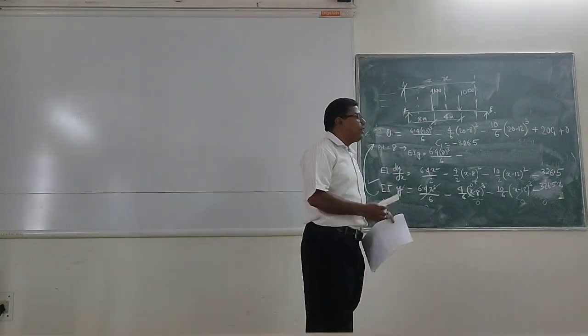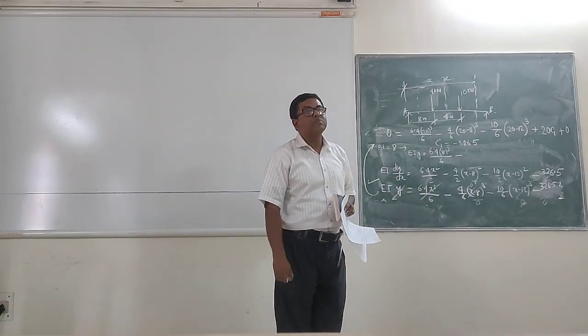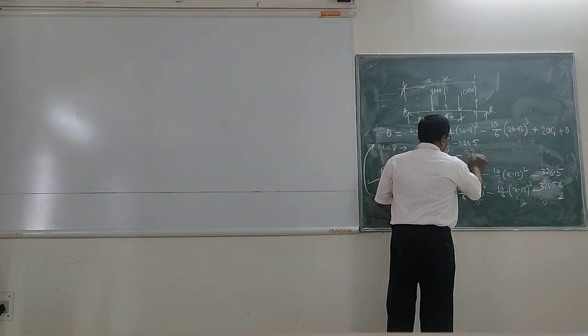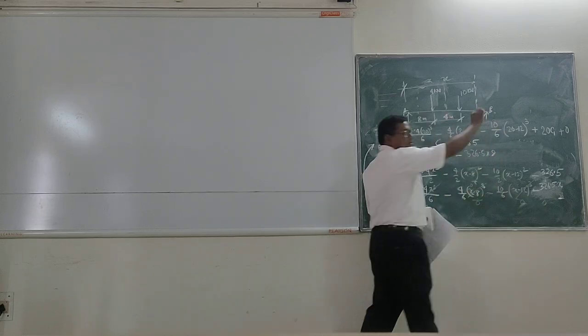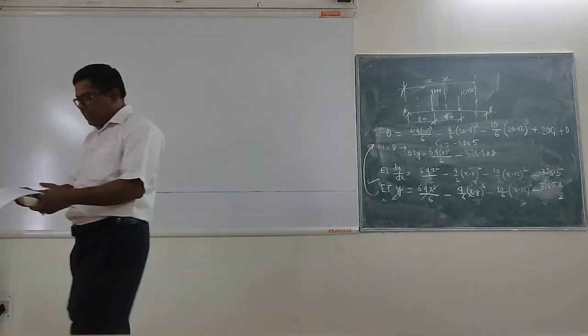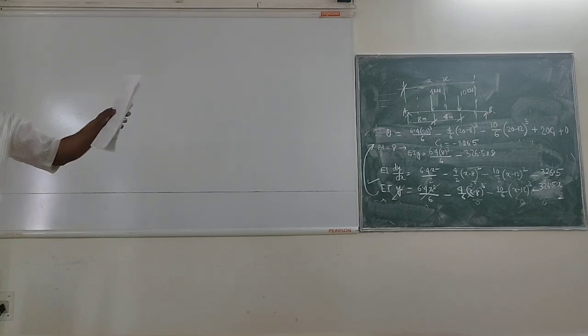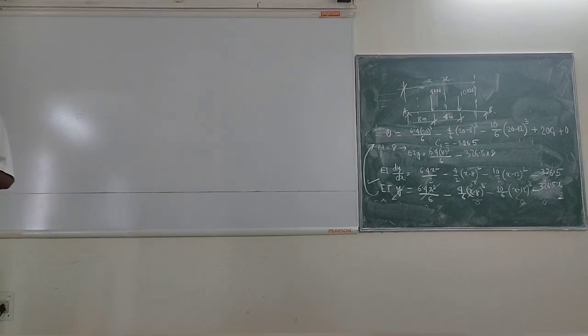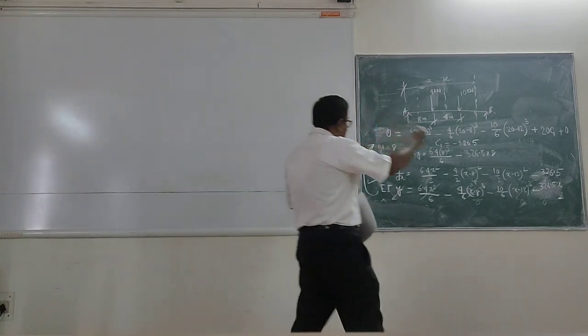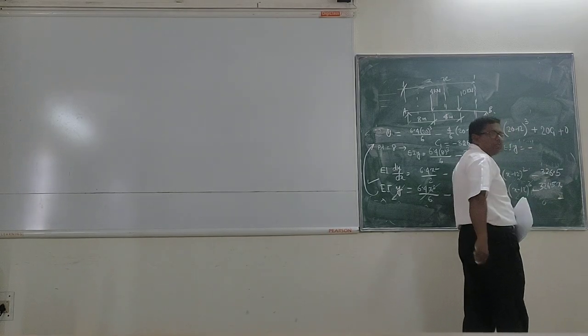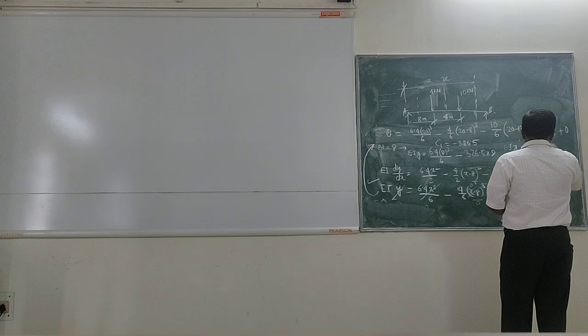After that, minus 326.5 into x. What will x be? 8. It will not become 0. Okay? So minus 326.5 into 8. This will be your deflection at the point where the 4 kilonewton load is, at 8 meter distance. It will be 2066, something like that. So if you calculate, you will get EI into Y is equal to minus of 2066, something like this.